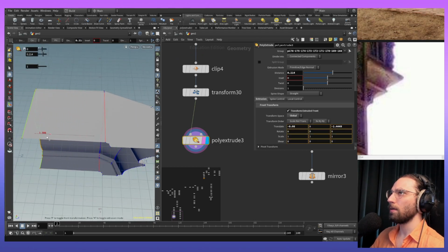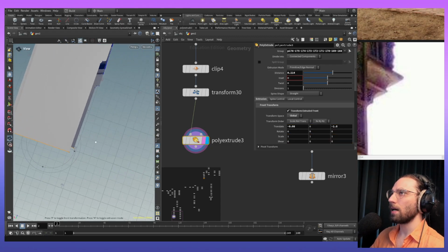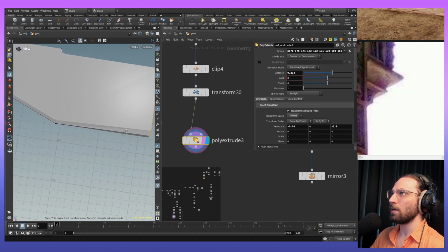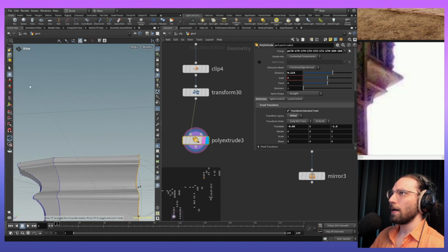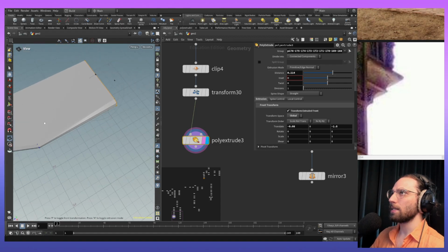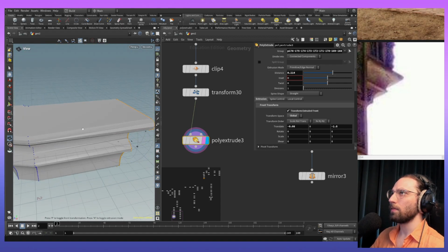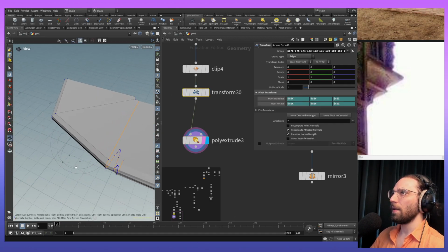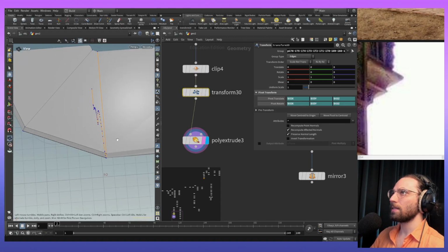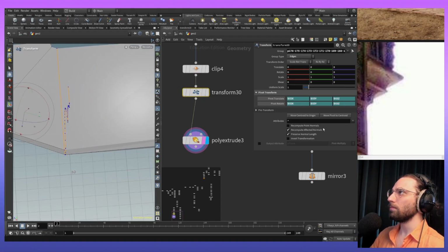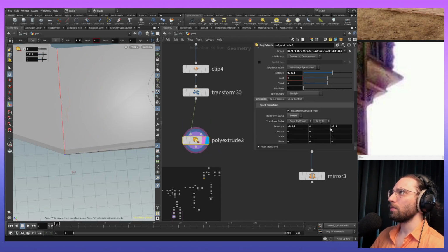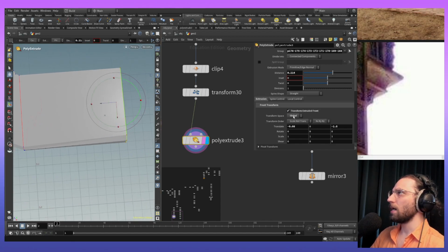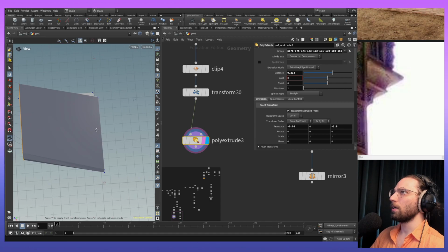So let's take that one in the x-axis, or in this axis at least. See, yeah, this is definitely happening. There's a primitive here that we don't want to be. But otherwise, there's more deformation right there that I'm not a fan of. I wonder what's that? Why is that happening? Now which one were we playing with? Okay, so in the extrusion itself, not in the transform. In the extrusion, there's this where you could change it from local to global.